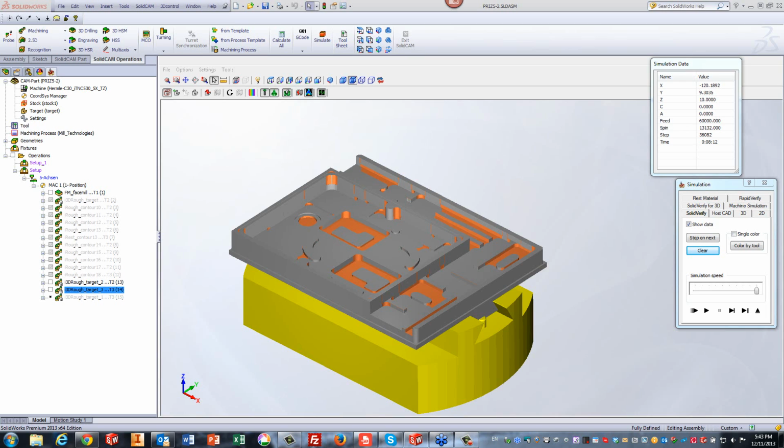Okay, does 3D iMachining cope with fillet radiuses between walls and floors? Yes, it does, because it still reads it as a 3D part. So when it sees that radius on the floor, it'll make that step on those corners as well. So it does deal with that. It's not a problem at all.